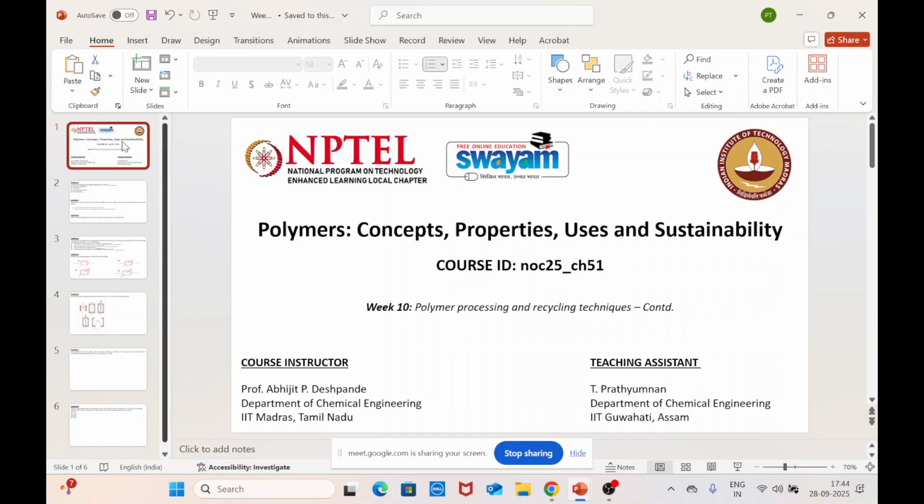These are the different types of post extrusion operations. First one is stretching, then you have rolling, and then you have blowing. In all these three cases, what we try to do is stretch the macromolecule. Only the way of stretching is going to be different, but the final purpose is the same. In stretching, you use mechanical force. In rolling, you use rollers. In blowing, you blow air into the extruded structures, and then expand them, stretch them, and this helps in the shaping of the product that we want.